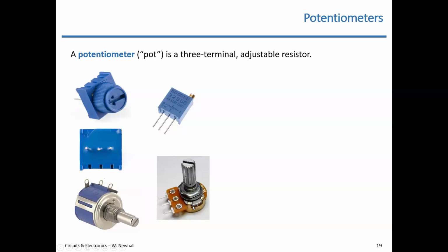This is a potentiometer. You can see the shaft. You can see it's knurled, so you put a knob on it. This might be through a panel, so you can put a knob on the outside and control the resistance, which we'll take a look at, and the three terminals here. The schematic symbol for a potentiometer is this. It looks like a resistor with two terminals, but you have this third terminal with an arrow. It's often drawn like this.